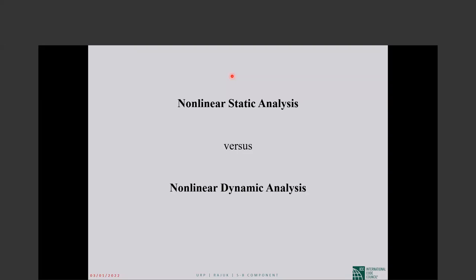For example, the earthquake happens somewhere, you have the records, you have the building characteristics, you go and model the building and apply the record and check whether the observed damage and the calculated damage are similar or not, and you get lots of good points about the modeling, for example, why the results are not the same. If I change the modeling of this infill this way, the results become similar, and lots of good points will result. But where we have the record.